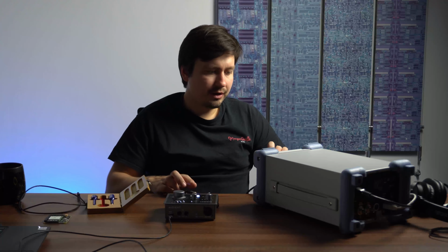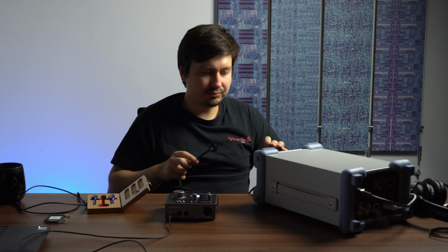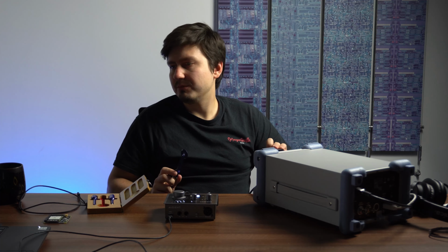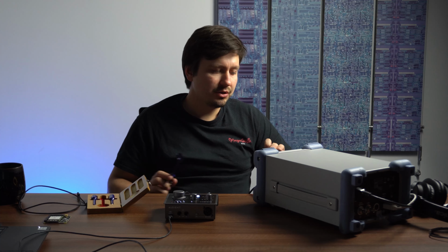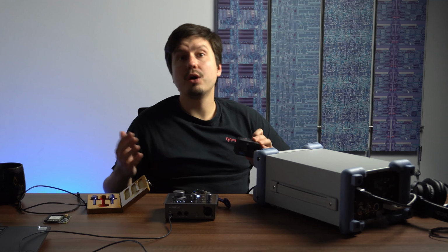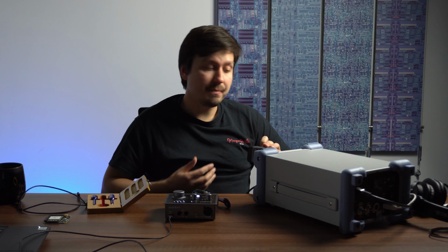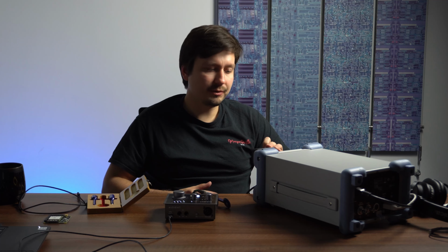So we are now having some ambient spikes that we are probably perceiving from LTE or some other spurious emissions. You would always have them in your system unless you are in an anechoic chamber. So this is kind of why we tend to go to an anechoic chamber.